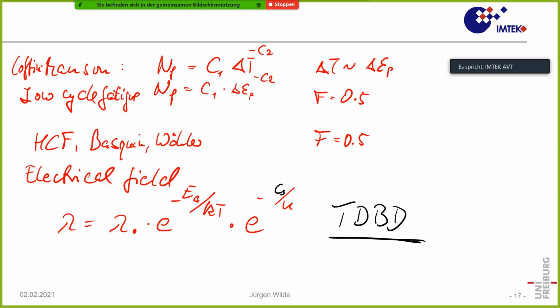On the other hand, you have an insulation against high voltage. So again, you have some plastic shielding around a high voltage cable, so that when you touch it, you will not get an electrical shock. But also such insulations will fail after a certain time if the electrical field is too high. So time to electric breakdown is a very important reliability aspect in many devices.